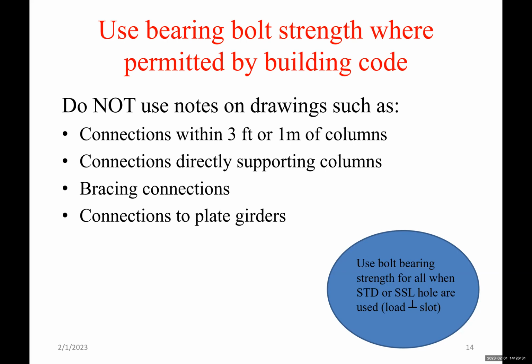Use bolt bearing strength for all standard or short slotted holes. Holes are used so loads are perpendicular typically to the slots. So, I mean, typically that's what's recommended. Standard holes or short slotted holes are easy for fabrication and for adjustments also during erection in the field.